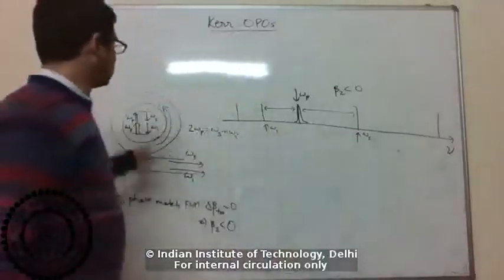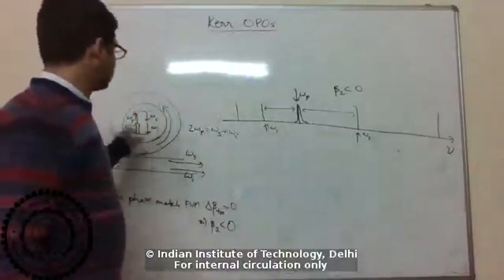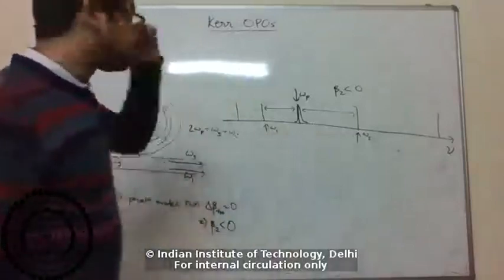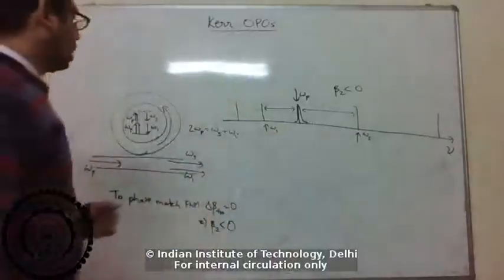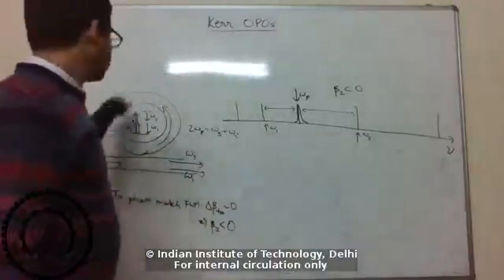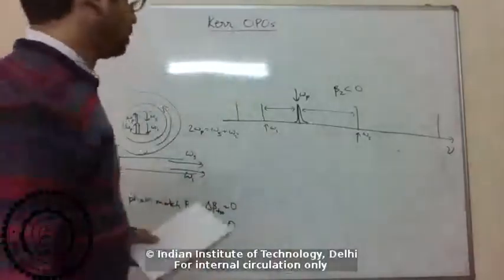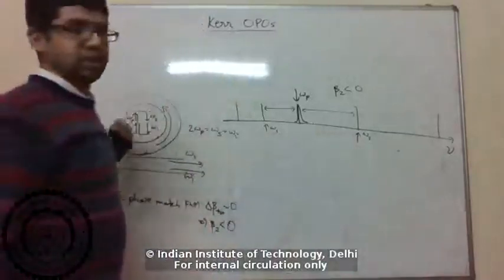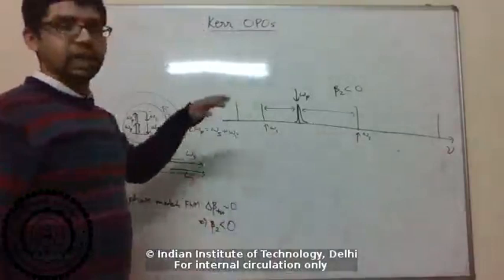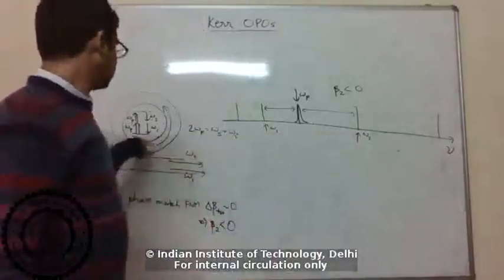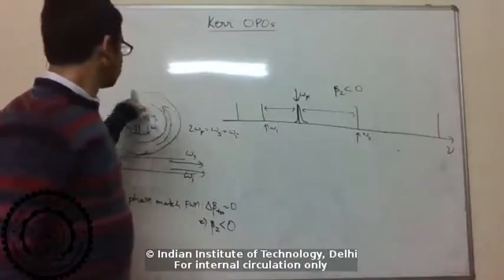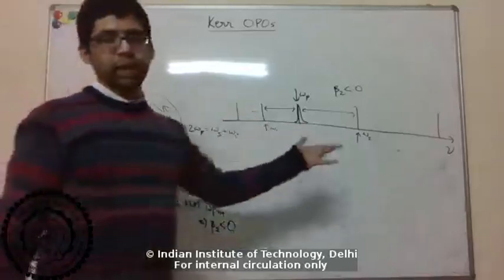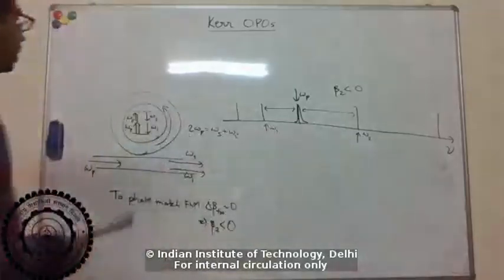We just took some propagation constant and the dispersion beta 1 and beta 2, and we took some round trip phase equal to a multiple of 2 pi. That phase was just the linear phase, e to the i beta z. For z equal to one round trip, where the round trip length is L, beta L equal to 2m pi is the resonance condition.